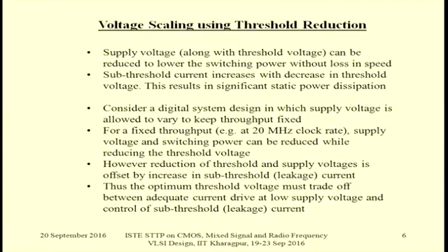But the danger is that if you scale down VT from 1 volt to 0.5 volt, the subthreshold current will rear its head. That means the subthreshold current increases with a decrease in threshold voltage, and this can be an irritating static power dissipation. The device is not doing anything, the phone is silent, but some power dissipation, although in the range of nanowatt, will constantly be there.